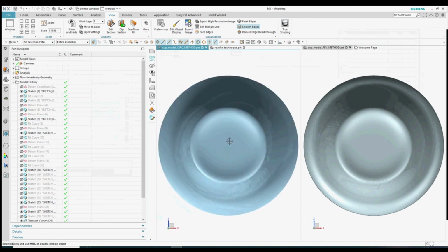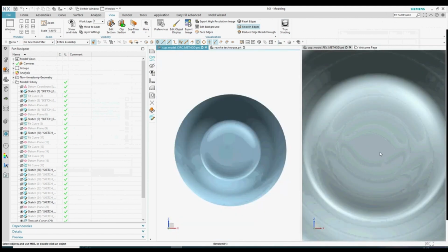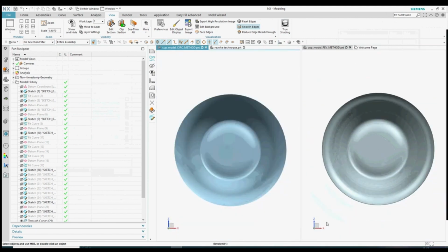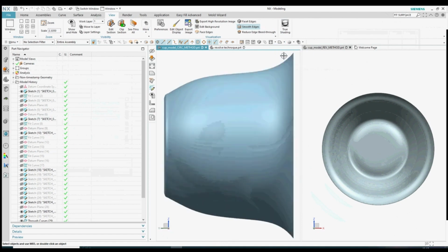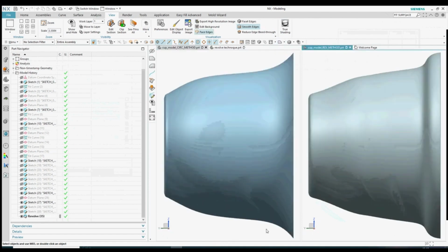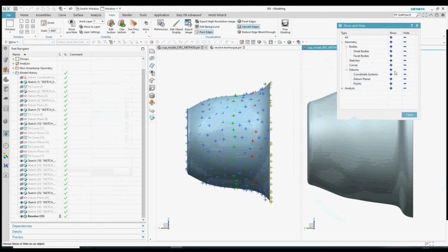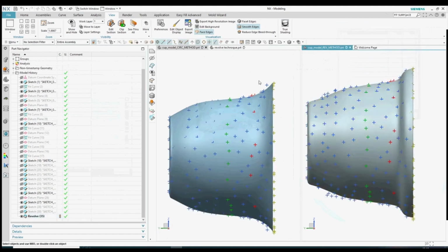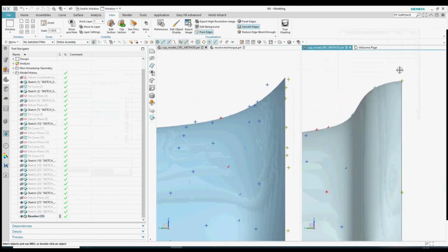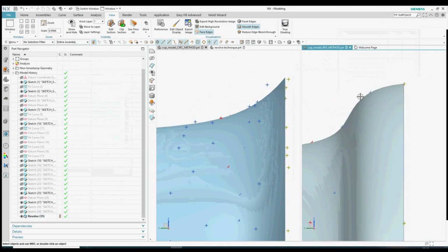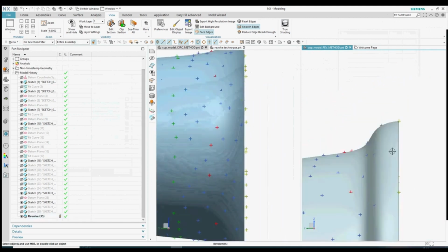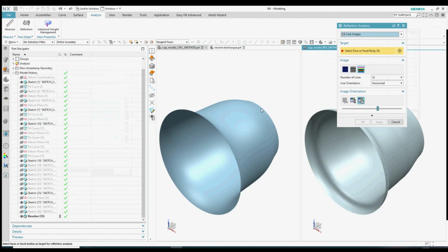The bluish model was created through the through curve command, and the grayish model was created through the revolve command. And if you look at the side view, specifically the open end of these two models, I would give points to the model that was created from the revolve function, which is the grayish model, because look at that front lip. However, if we check the reflection analysis, now what we want to see is undisturbed lines.